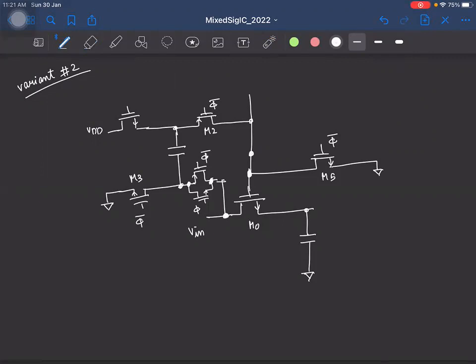Okay. So obviously, since it is trying to pass a voltage VDD, to turn the switch on, it is not enough if we connect this gate to VDD, right? So we need to connect this to 2 VDD to turn this on. But please note that to turn the switch off, so let me draw the switch separately here. I'll call this M1. This is VDD. When this switch is off, this voltage is connected here, right?